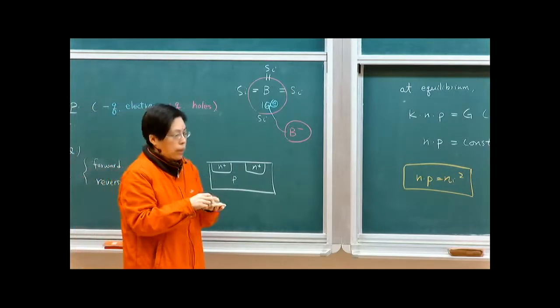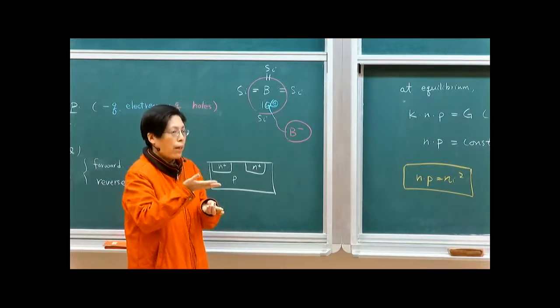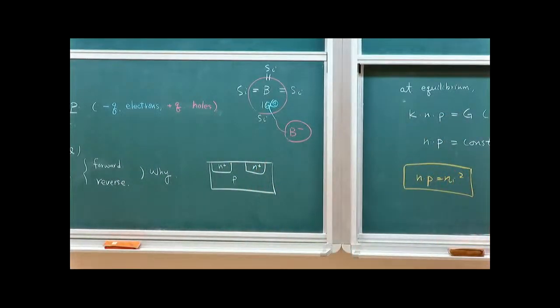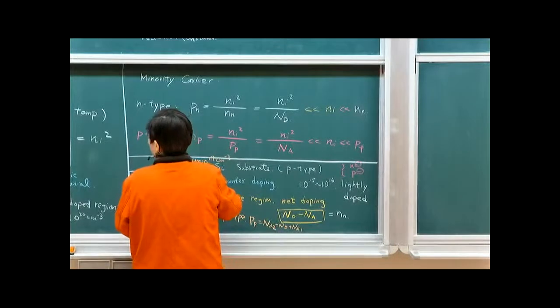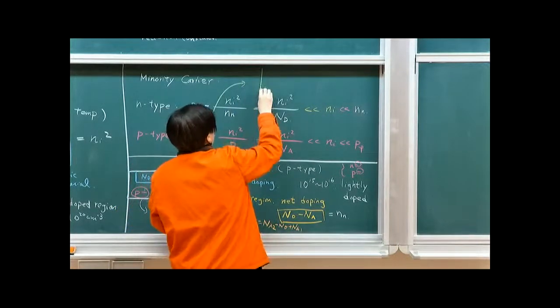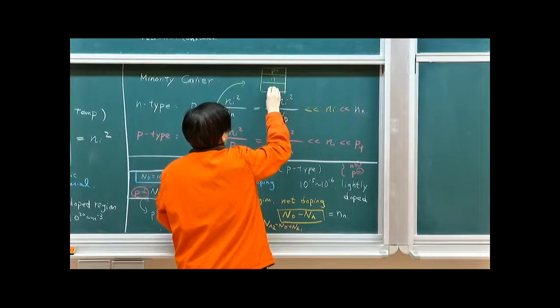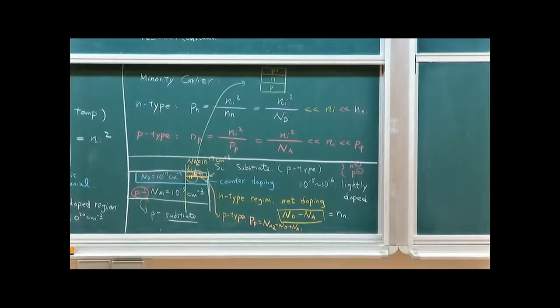Then in integrated circuits, you will see many counter-dopings. It will contain layers of dopings and then counter-doping of materials and allow us to form certain structures. In this case, if I'm magnifying it and drawing it out, this will be a P plus region, N and P. So that will give us a bipolar junction transistor. So that's what a BJT is. Okay? So through different modules of counter-doping, we'll be able to form structures like transistors along the way by using these techniques.